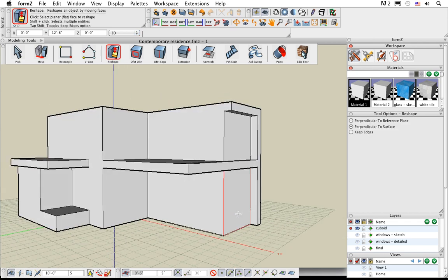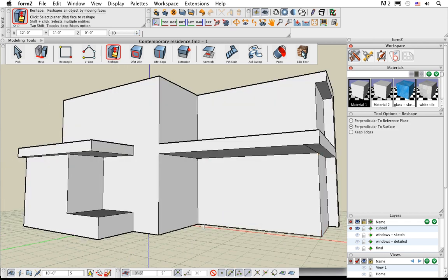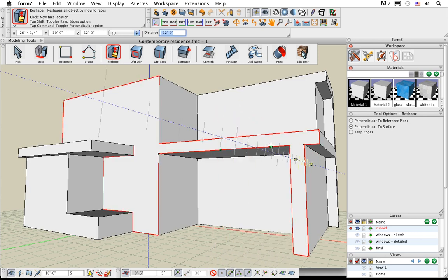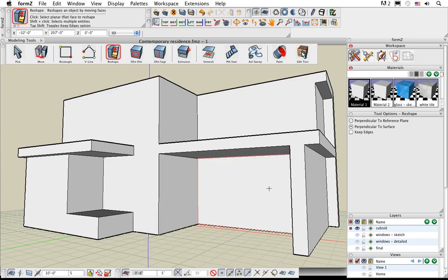All right, let's go into front view here. I have a nice view that's saved here, my home view, sort of 5'9" from the front of the driveway here to get sort of a perspective view as we're looking at this building. And I'm going to add another wall on the side here. So once again, just use Offset Segment, whatever distance I want, and then reshape that out. And of course, to make sure it's flush, I can snap it right to the edge of that existing roof, and everything's nice and healed for us.